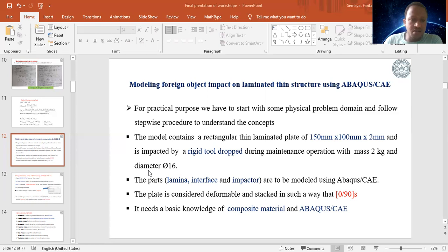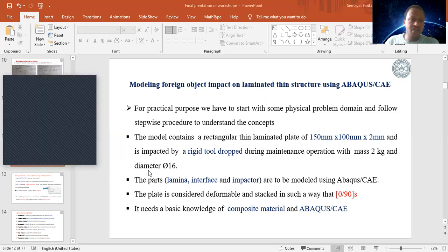Now we can trim unnecessary parts. Actually, before that, let me make it a closed form and then trim the extra parts. So 1/4 of the circle is created now. So let's revolve this by 360 to create it.